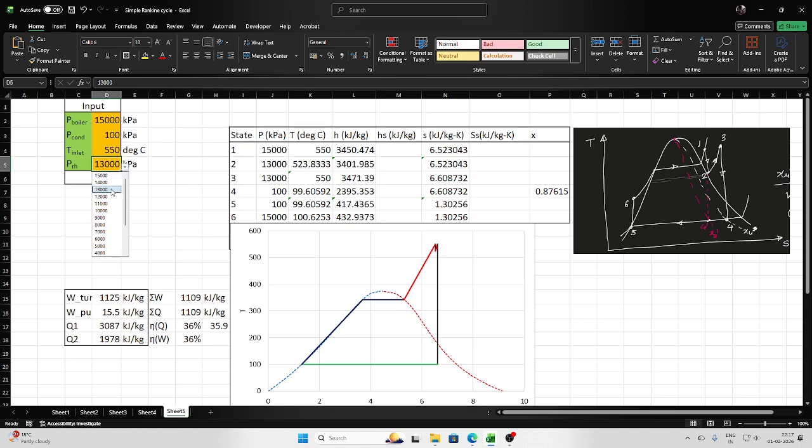You can also see that this particular line is going away. The work and efficiency I'll discuss later, but just notice how this comes into picture with reducing reheat, and how this line moves to the right, resulting in improvement in the dryness fraction. From 130 to 120, it has again moved, and now you can see a little bit of reheat. From 120 to 110, again there is improvement, and this is now coming into picture.